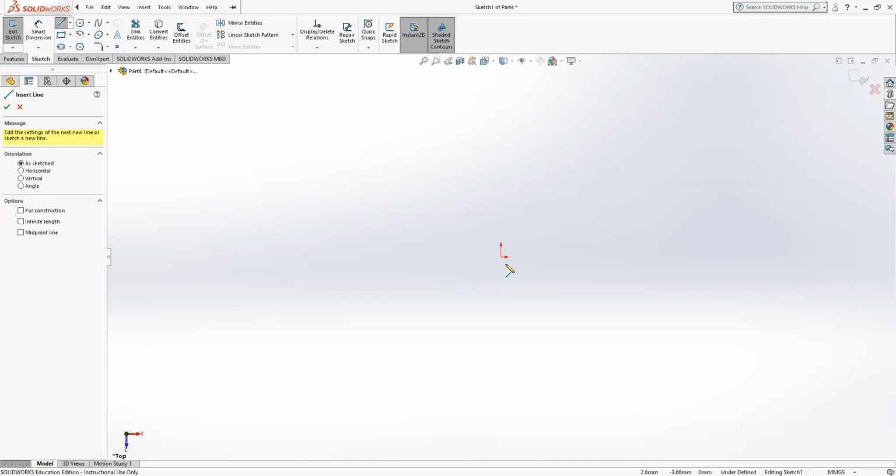So anyway, you start with a line drawing, and it will show you. You also see that when you're right at that intersect, you also get another little yellow square there that shows you that you're at a perpendicular intersect. So all of these are little indicators that you'll get when you're drawing that let you know that you just came up to a line. It will kind of snap to it, and it also lets you draw 90-degree angles and things like that a lot easier.